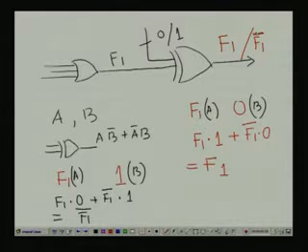So, in this way I can get the complement of the output function. This is another programmability we have added here, just by feeding a 0 or 1. This can be a control line. If it is 0, as it is, I will be getting the function I actually want, the output of the OR gate, and if I want the complement, then my control line is 1, and I will be getting the complement of the output.